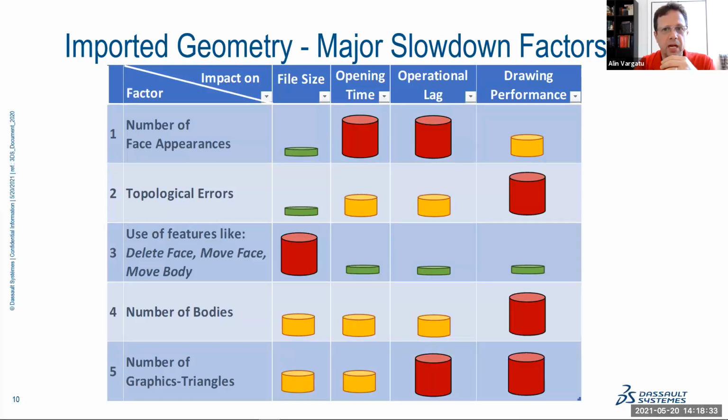And those are very hard or impossible to dimension, impossible to balloon, impossible to attach nodes. If you save the drawing, it's going to take forever if you save the detailing data. So this became my number one enemy when I help my customers who are dealing with drawings. The other thing that's good to know is that if you run delete face, or move body, you are increasing significantly the file size of a part.